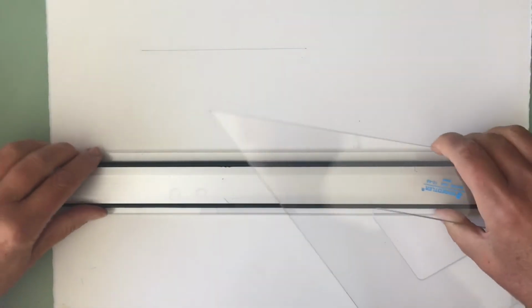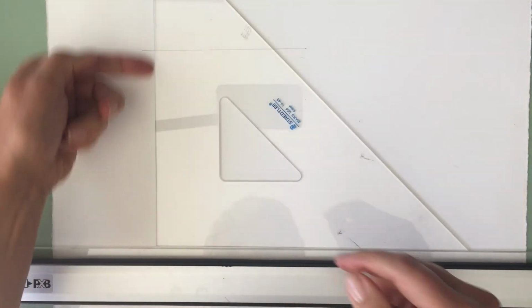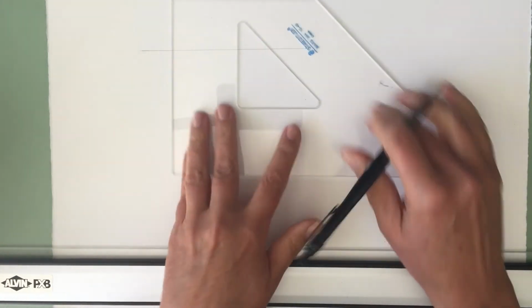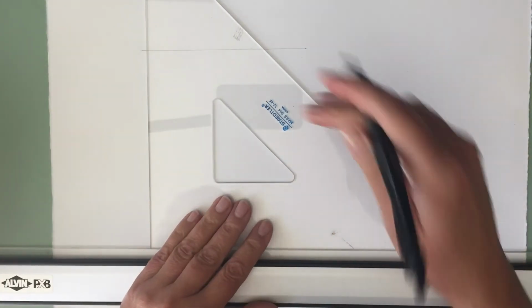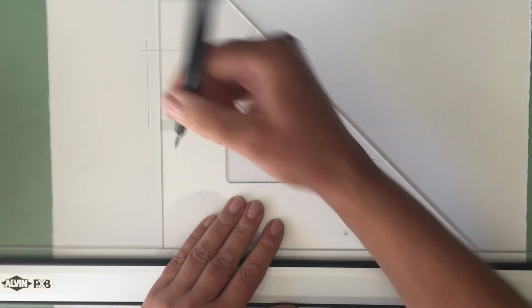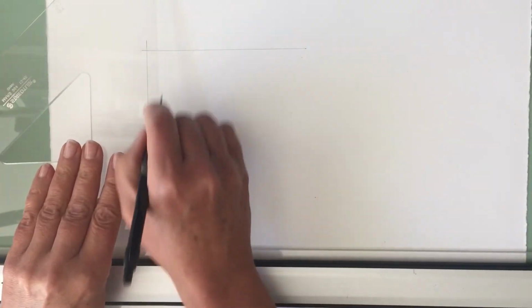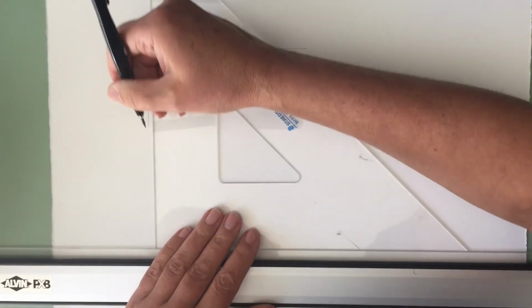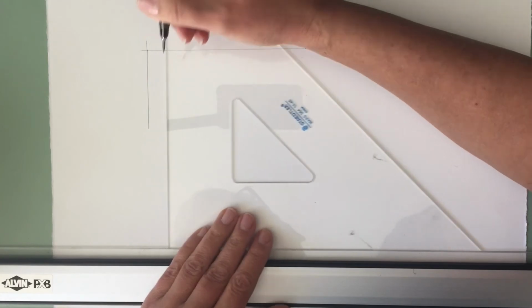So now we want to draw a vertical line. In other words, a line that comes down here, and that's what this is used for. I now will square that up on the parallel rule. So if I want a line to come down that way, I don't guess and do this anymore. I just line it squared up with my parallel rule, and I draw a line in that direction, like so. And you notice that I didn't actually draft that line like this. I have the ability now to always see where I am going if I draw it like so.